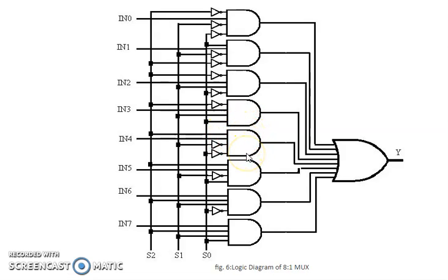So that's how the realization of any multiplexer will be done with the basic gates. We take all possible input combinations across these AND gates in order to activate the particular AND gate to be enabled. However many inputs there are, that many AND gates we will have. Then the outputs of the AND gates will be driven to the OR gate.